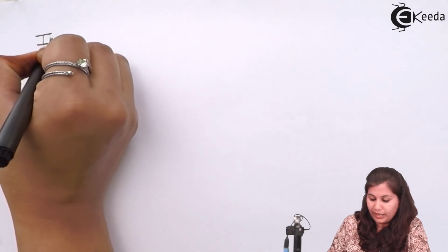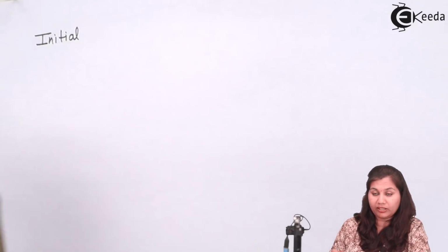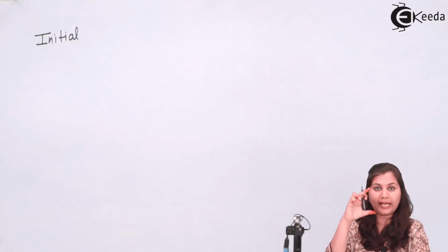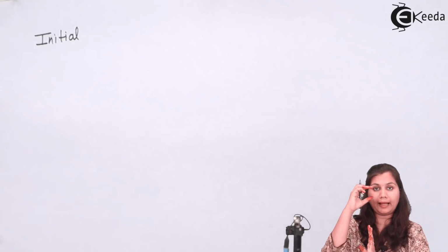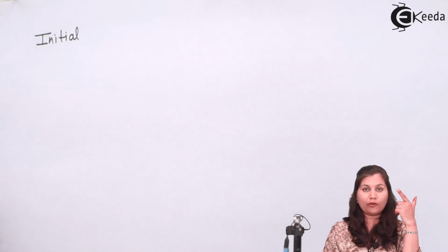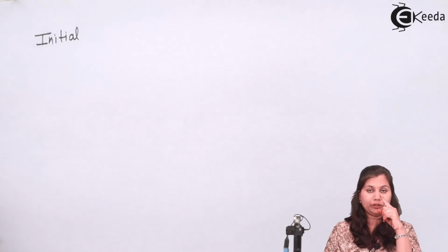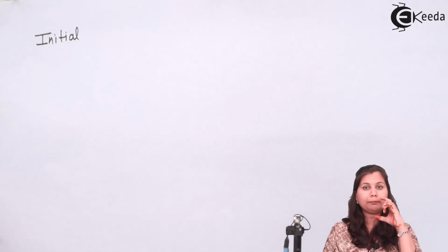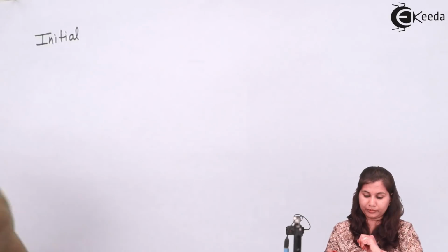So the first time when we have increased the level of the mercury up to the cutoff point, the volume of the gas which is trapped in the bulb and the measuring capillary will be equal to the area of cross section of the capillary tube into its height, meaning the total volume of the measuring capillary, plus the total volume of the bulb.